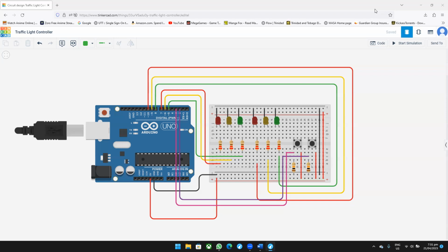Just a small introduction. Traffic lights are an essential part of modern transportation systems, regulating the flow of vehicles and pedestrians at intersections. In this project, we designed and built a traffic light system using the Arduino and LEDs. The system will have 3 lights, red, yellow, and green, and will operate in 2 modes, normal operation and pedestrian mode. We will connect the LEDs to the Arduino board using a breadboard, jumper wires and 220 ohm resistors to limit the current flow to the LEDs.